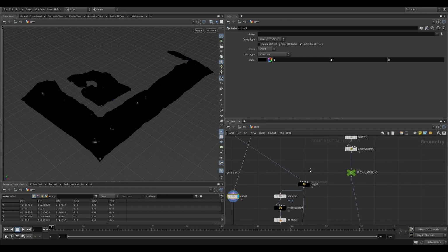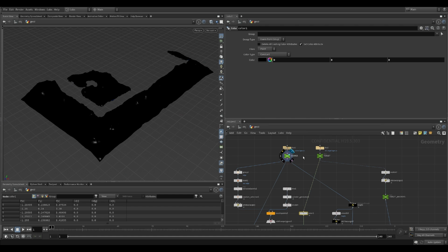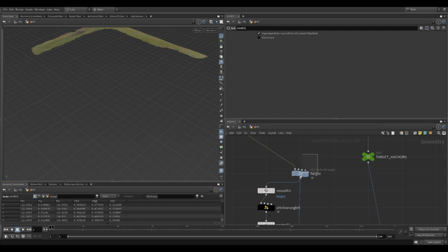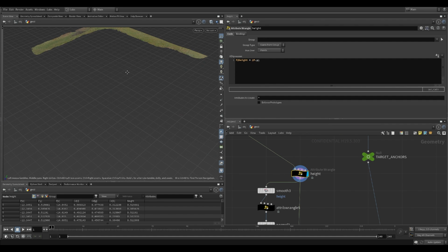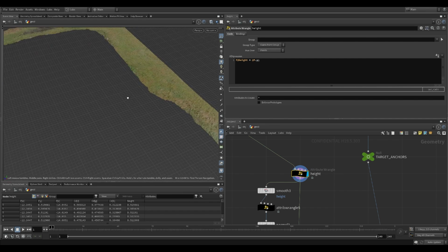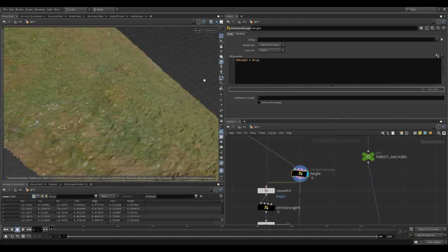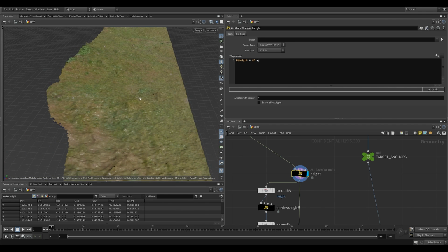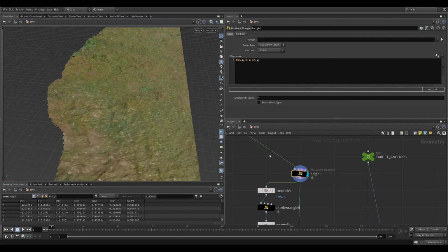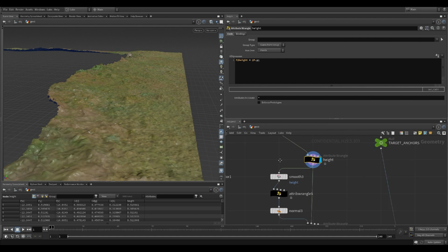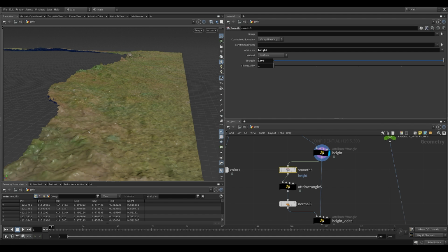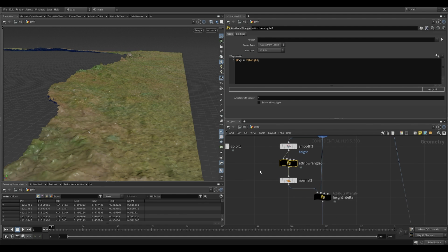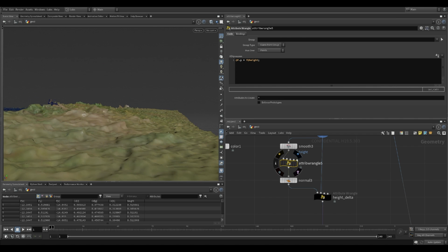The other thing we're going to do is to prep the source so that it has the delta attribute we want. In this example, I'm doing it slightly differently. Instead of smoothing out P, we can smooth out any attribute. That's sort of the point. Use spectral transfer of any attribute, not necessarily just the position. Here we create this height attribute based on the height of the P. Then we smooth out this attribute with a very strong strength. Then we modify the height based on the smoothed out result.